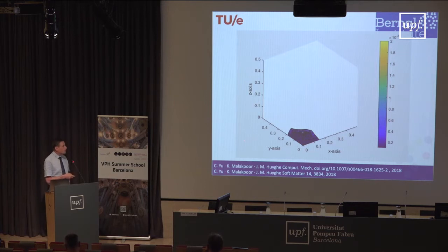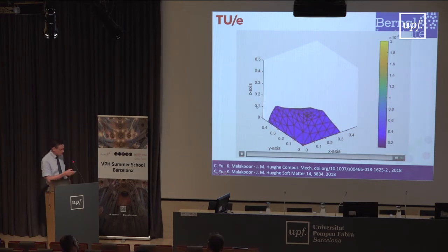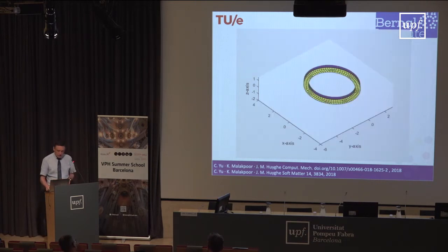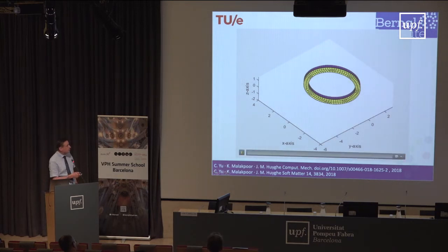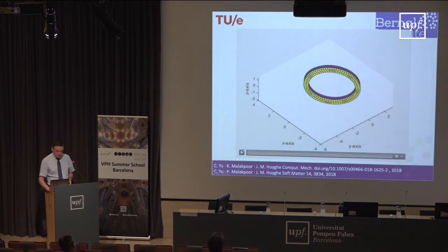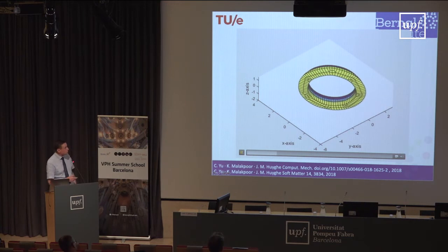So we use this formulation, and we are going to look at a small piece of gel and allow it to swell. And you see, this is what happens. We have tetrahedral elements in 3D, and it can swell to multiple times its own volume, and we get very stable results. And another example, which is maybe even more illustrative, is a ring fixed to a fixed surface, brought to swell, and it goes into surface instability.